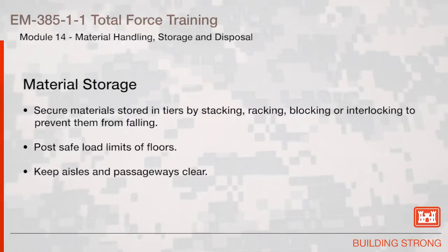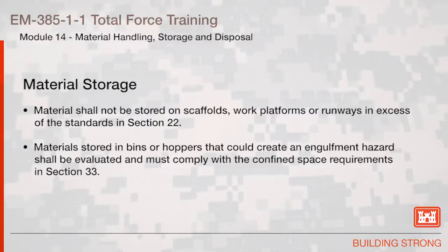Secure material stored in tiers by stacking, racking, blocking, or interlocking to prevent them from falling. Post safe load limits on floors. Keep aisles and passageways clear. Material should not be stored on scaffolds, work platforms, or runways in excess of the standards in Section 22. Materials stored in bins or hoppers that could create an engulfment hazard shall be evaluated and comply with the confined space requirements in Section 33.